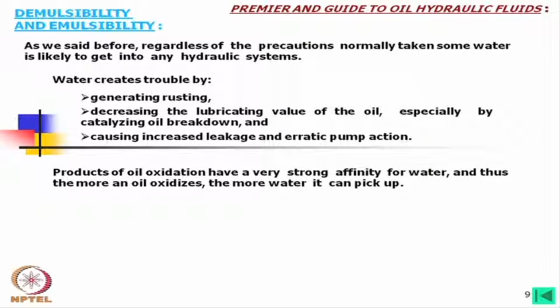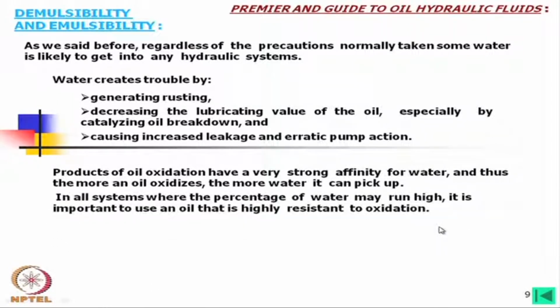Sorry, in this case for water there is no cavitation, but it will change the oil specification, like API gravity and viscosity, and then pump action may be erratic. Products of oil oxidation have a very strong affinity for water, and thus the more an oil oxidizes, the more water it can pick up. You see, this is another point, it can easily take water due to the oxidation.